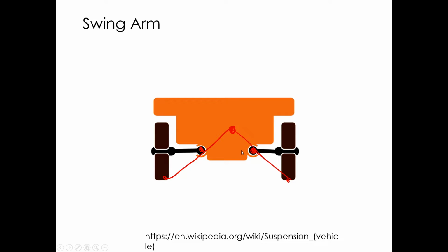Your instant center is very short. Actually, would it be from there? I have to think about this a little second. Yeah, no, that's right. So you don't see a lot of swing arms. Biggest problem, the instant center is right here. So this tire is bumping up and down against a really short moment arm here. So it's going to change an angle. It's going to camber a lot as it bumps up and down, and that provides all sorts of camber control issues going around turns. Yeah, you saw some old cars like Beetles and things like that use this, but it's pretty rare.